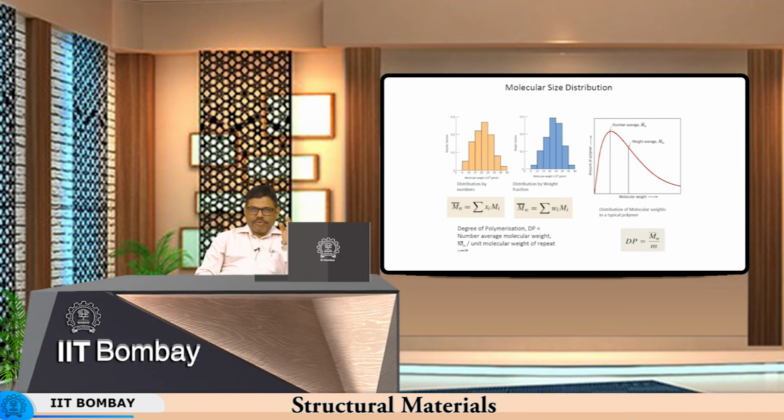But in case of polymers, the melting point itself varies very significantly depending on the molecular weight. So, it is possible that in the same quantity of polymer, let us say you have a number of polymer granules, at a given temperature some polymer granules have molten, some have not.